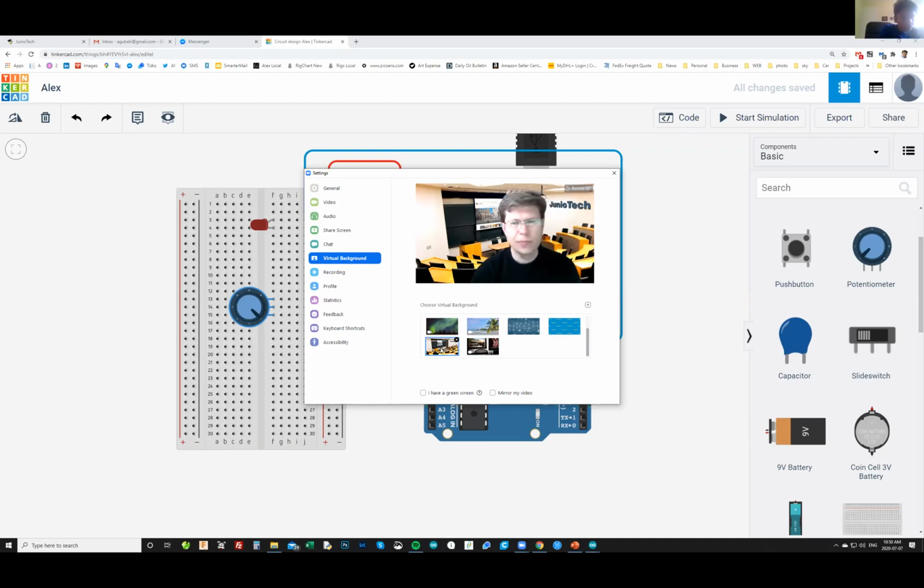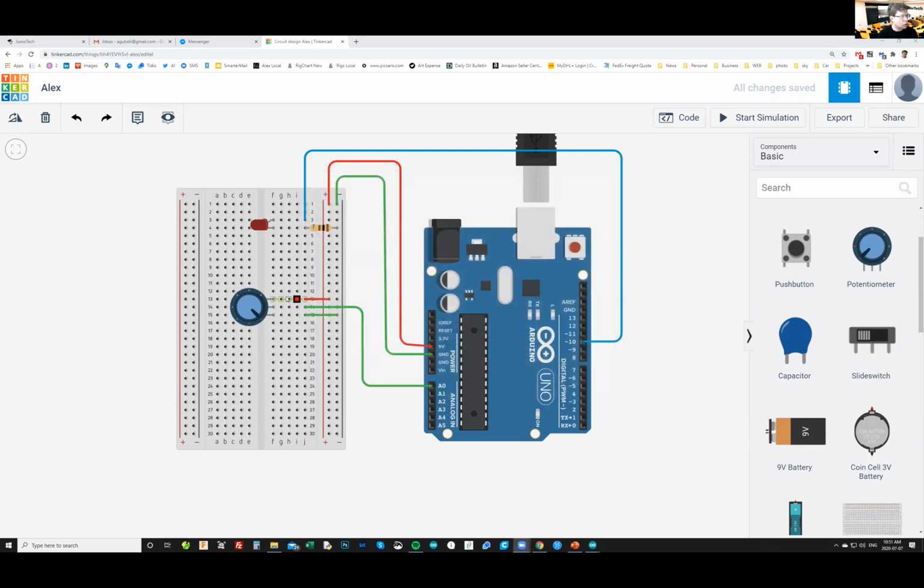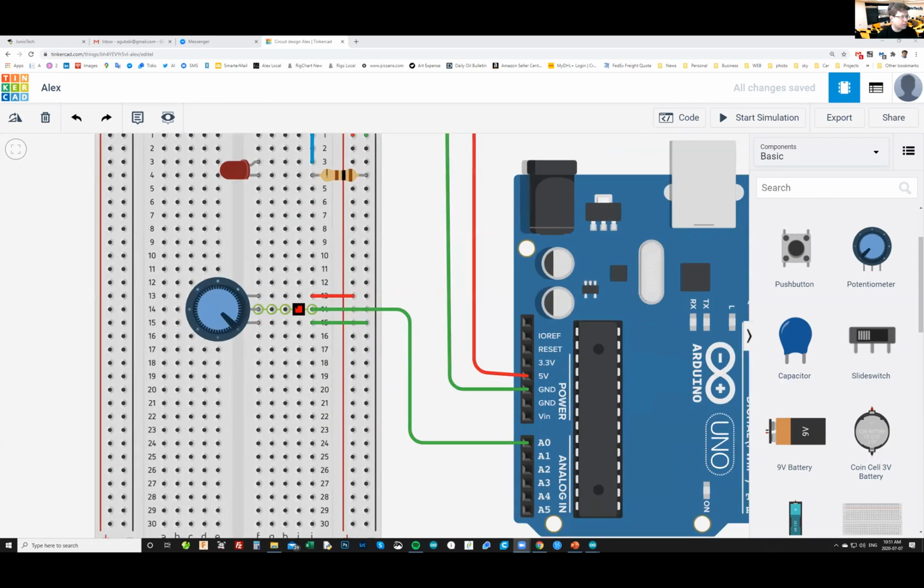Wait, does the pin go on top? No, the pins have to be at the bottom and the knob should be on the top, right? Yeah, the knob. I meant the knob. Alex, do we connect the wires? Yeah, you plug the potentiometer into the breadboard, and then you need to connect the outer legs to a positive and negative bus on the breadboard, like I am showing here.